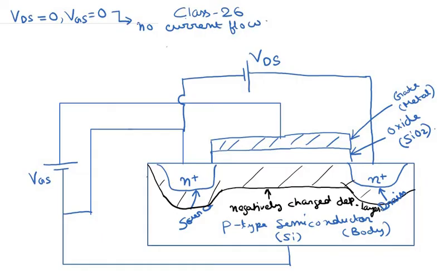Now when we increase VGS, this depletion layer grows thicker and more charges are exposed, or more holes are repelled away from the surface. So now the depletion layer contains more charge, and when we keep on increasing this VGS, one point of time would come when all the holes from the surface, that is from this region, have been repelled.